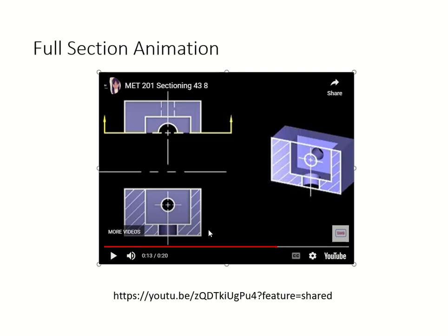same pattern, equally spaced. Don't do it like one line is close to another line. If you give about, let's say, 2 millimeters, you go 2 millimeters, please. And we complete the full section view. So this is your full section view. Of course, don't forget to put back the removed part right on top of it.